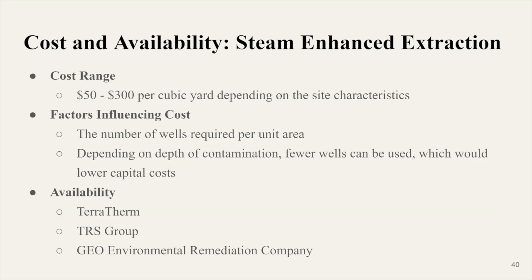For the steam enhanced extraction, cost estimates range from $50 to $300 per cubic yard, depending on site characteristics. The most significant factor influencing costs is the number of wells required per unit area. This is directly related to parameters like geology, permeability, and depth of contamination.